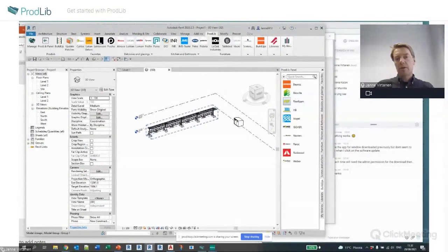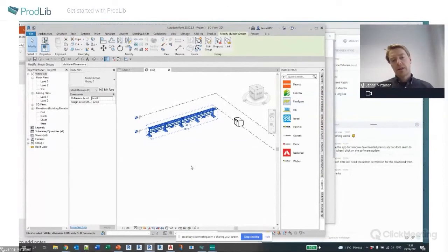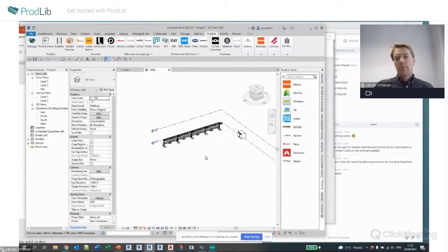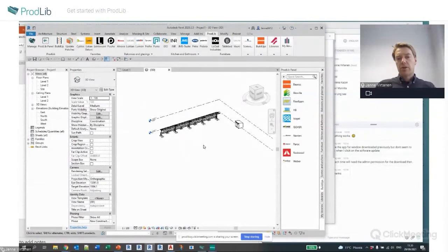This was already something a bit special in that sense, that to create this kind of object as a Revit family that does everything of this one, it gets really heavy. The file size is very big. But what we have done here is that we actually split it to smaller segments that we can add module by module and then just create a group out of this content. But we have some other functionalities as well that we can apply.